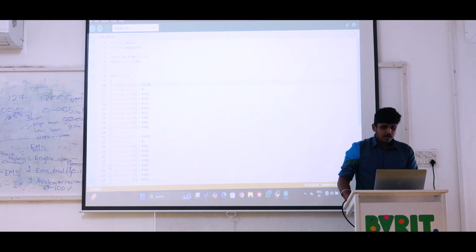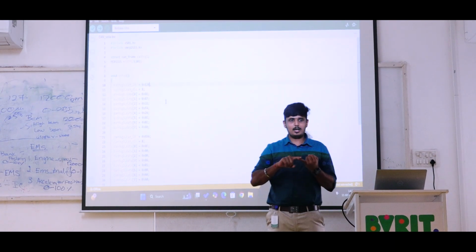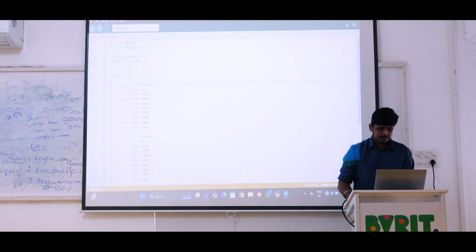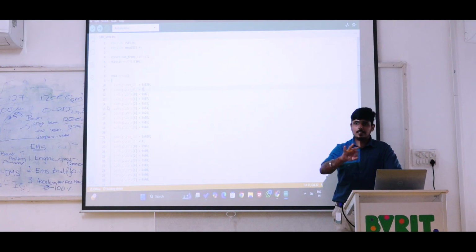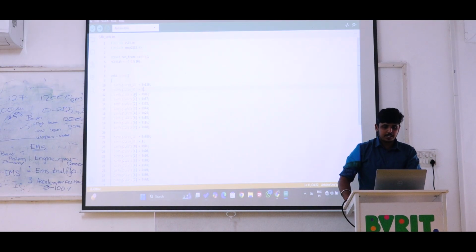In that 120 we are having only 3 DLC: lock, unlock, tailgate. So I am changing the DLC length as just 3. Yeah, 3 signals are there now, so that's why I am changing the signals as 3. Data length, I am going to transfer only 3 messages. I need only 0, 1, 2. Other things I am just cutting.